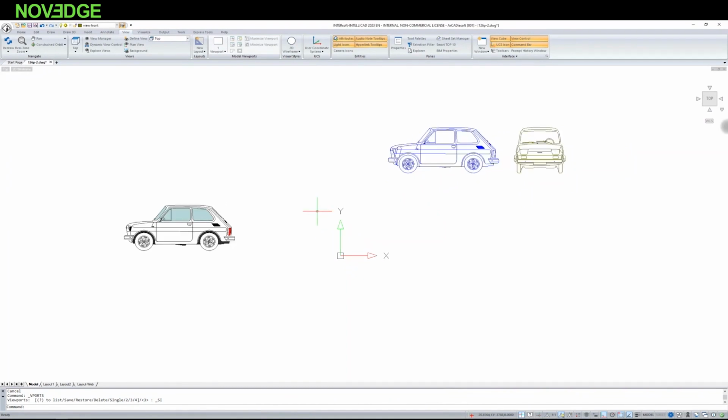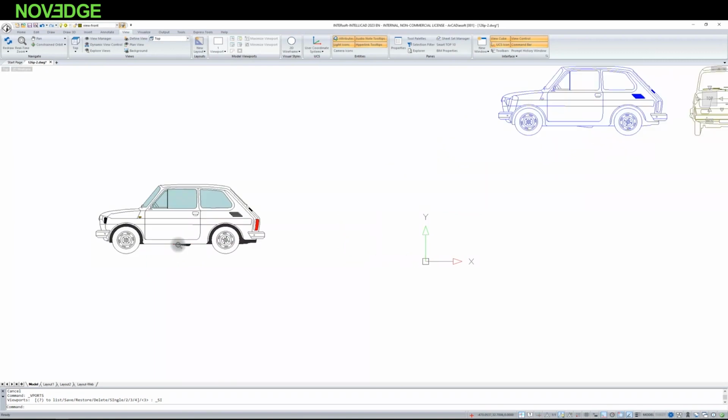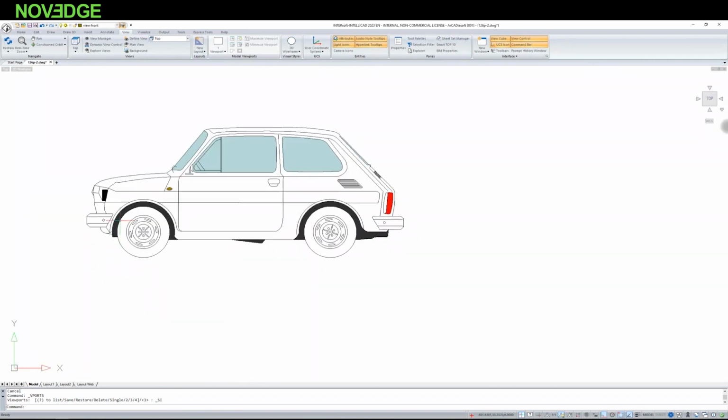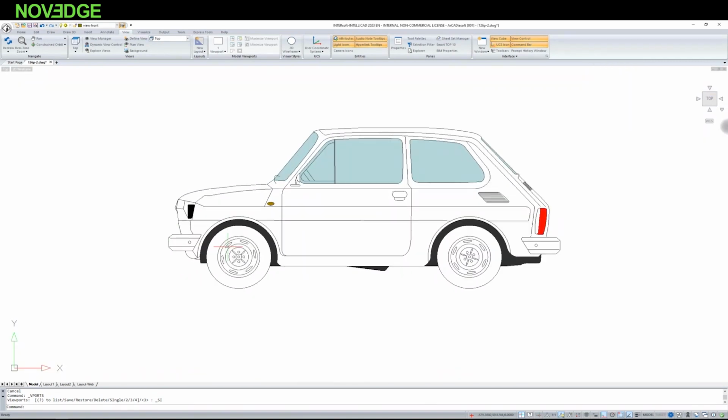Viewports in the layout and viewports in the model are a bit different because in the model they are only part of a drawing representation, and viewports in the layout can have different scales additionally defined. In a model, it is always on a 1:1 scale, and whether it will be in one viewport or in 3, this model is always shown exactly the same way. While on the sheet, you can show it differently.